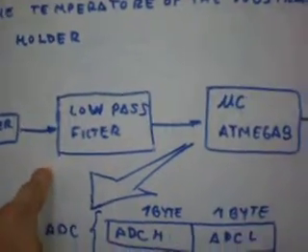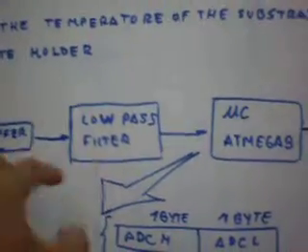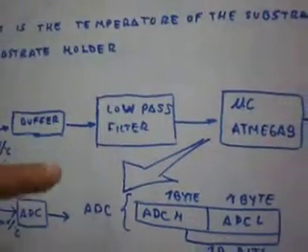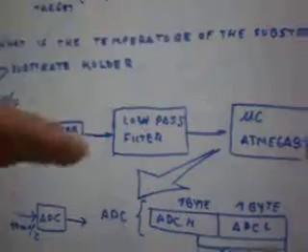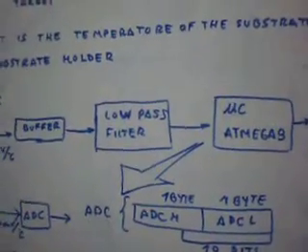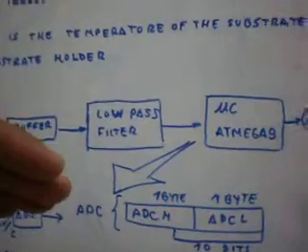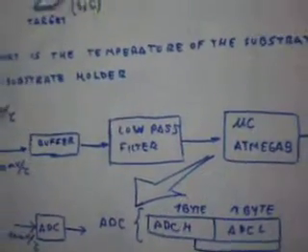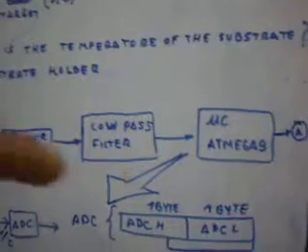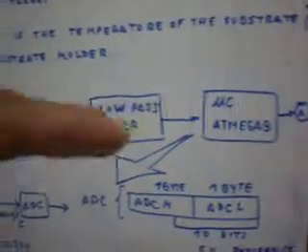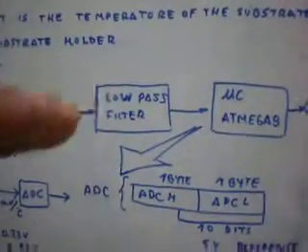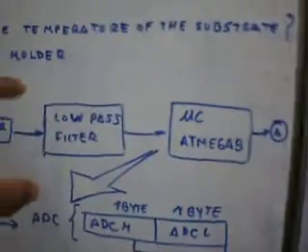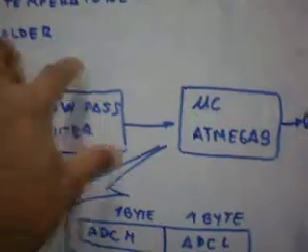In last versions, if you remember, we suddenly obtained, for example, 23 degrees, and suddenly it changed to 24, then 35, 36, or suddenly 16, 17, and it's not okay, because the temperature couldn't change so quickly, and especially couldn't change as a random expression. For this reason, it's necessary to work with the low pass filter.